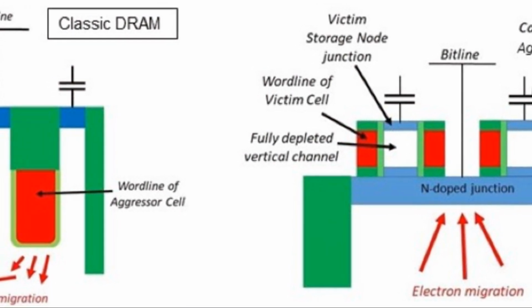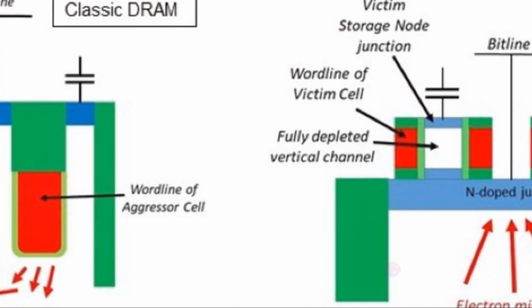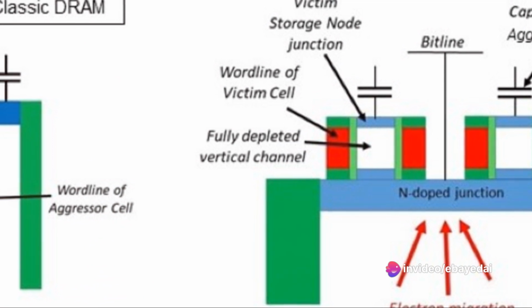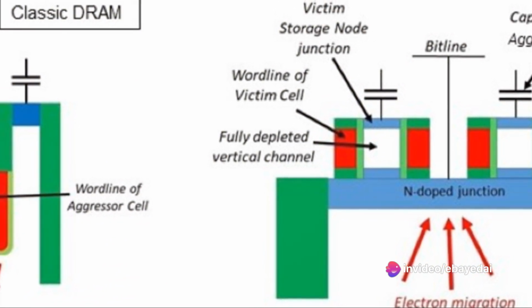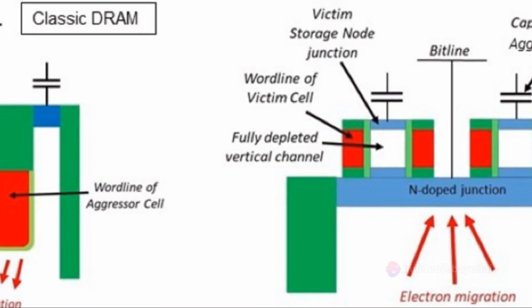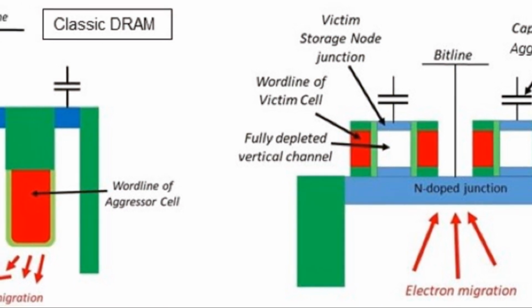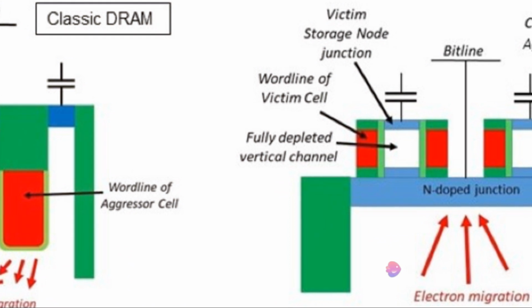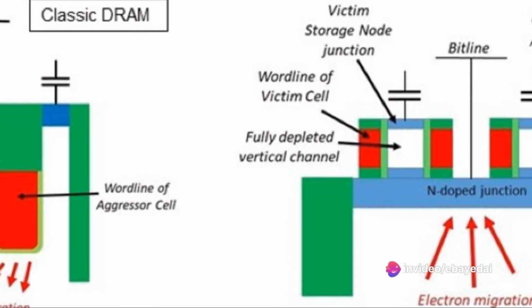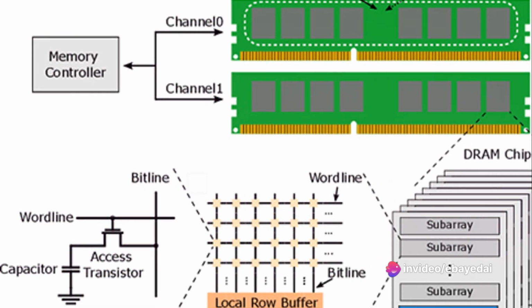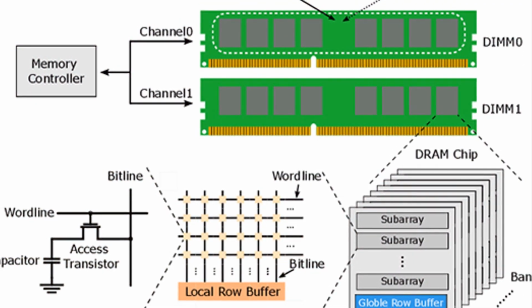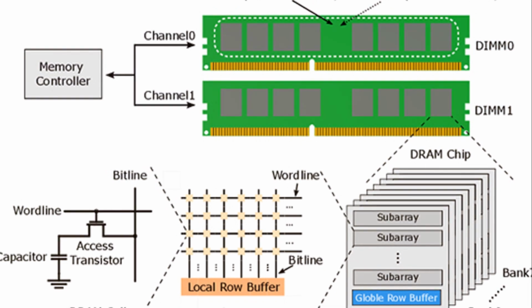in which individual memory cells interact electrically between themselves and other cells near them by leaking their charges, possibly changing the contents of nearby memory rows that were not addressed in the original memory access. This circumvention of the isolation between DRAM memory cells results from the high cell density in modern-day DRAM caches and can be triggered by specially crafted memory access patterns that rapidly activate the same memory rows numerous times.